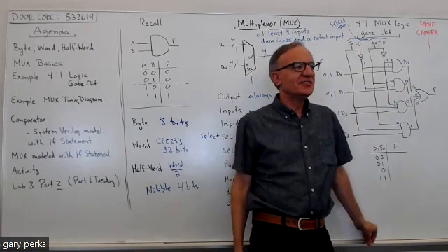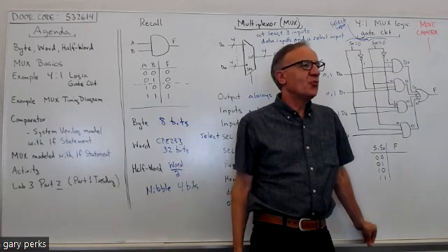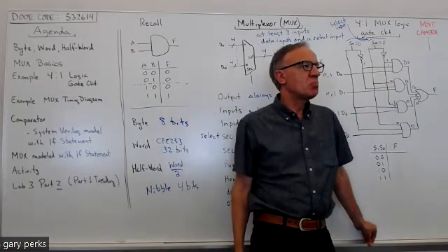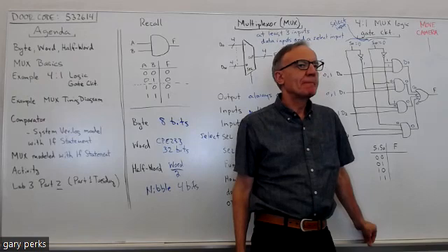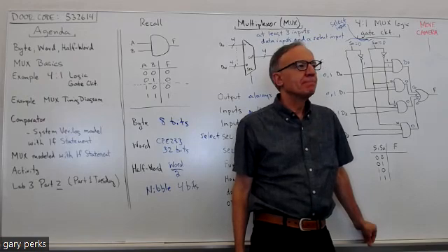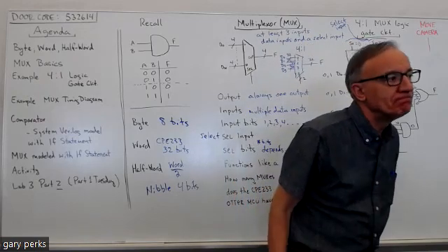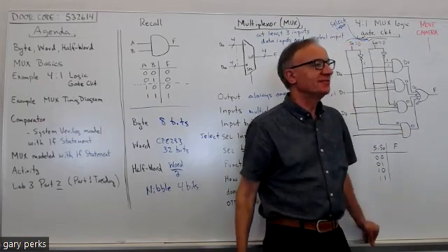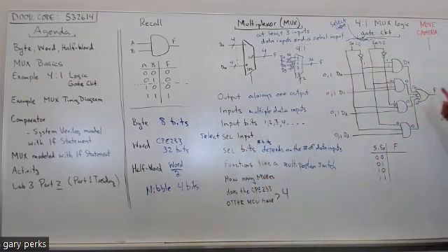Yeah, it's like a summation. So when do I get a 1 out of an OR gate? Yeah, at least one 1, right? The only time I get a 0 out is when all the inputs are 0. So you see when D0 is a 0, I'll get a 0 out. When D0 is a 1, I'll get a 1 out. So that means our output is just D0.